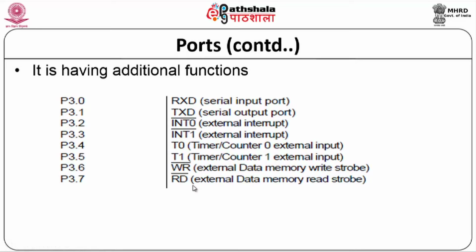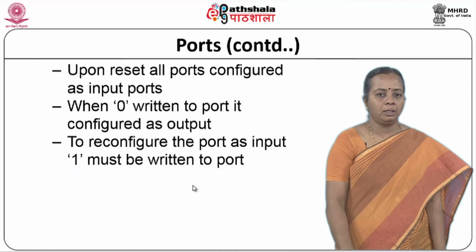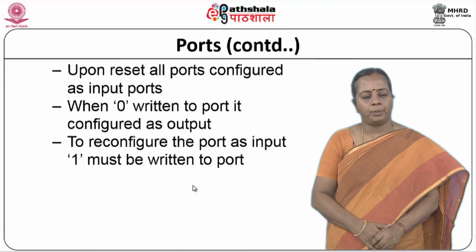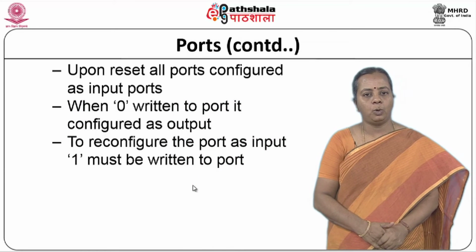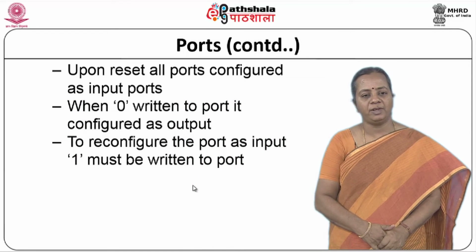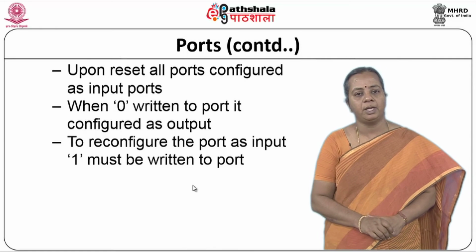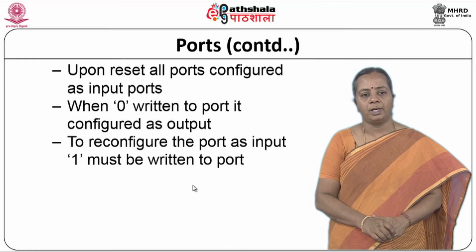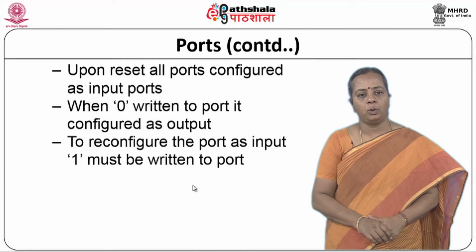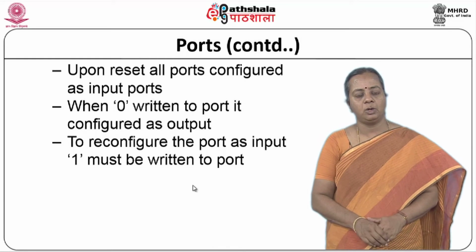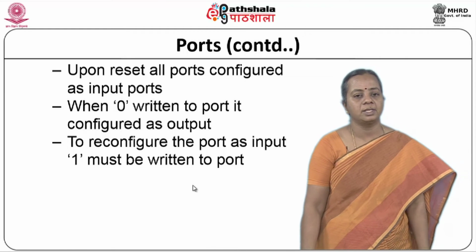If I am not using all these functions, I can use these pins as IO pins also. When you are looking at the ports, usually all ports are configured as input ports. If I am resetting, or starting at first, it will act as an input port only. If I write a 0 to that particular port, then I will say that it is an output port.